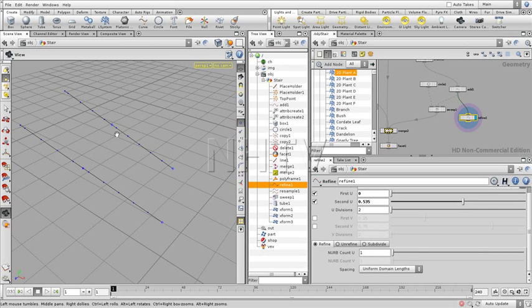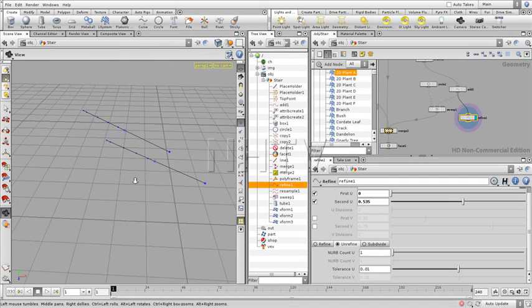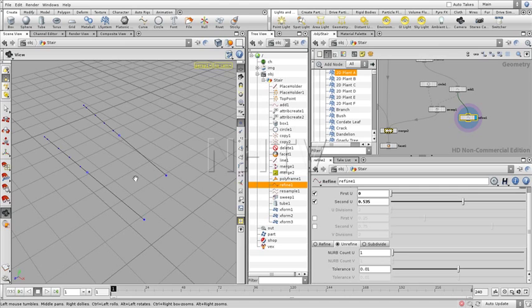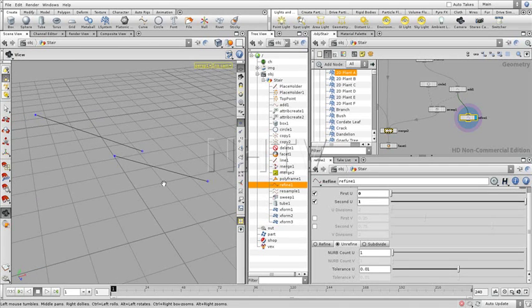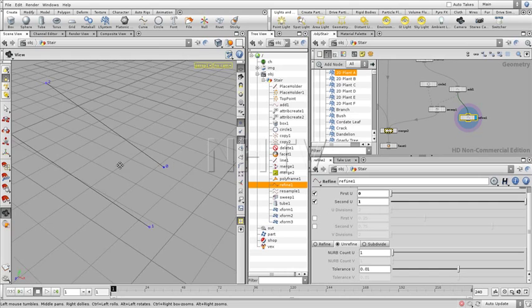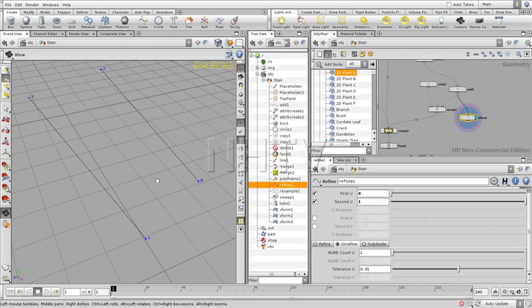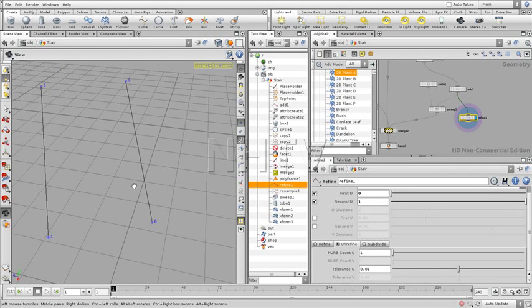So using those UVs, and since I'm working only on curves, I only have U, I can set a certain range where this operator has to have its influence, as you can see with these lines when I start moving up and down. So let me bring this just to the first U, and the second U I'm going to keep more or less over here so that you can see the difference. So what we're going to do is unrefine what we have over here. And by unrefining, you see the result immediately. All the points in between are just being removed. So now I can make sure that everything is clean by setting that selection from 0 to 1. Again, like that. Okay, so we have two lines now with 4 points and a set of primitives.